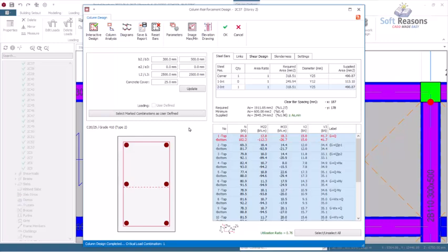You know, this column is actually carrying load, because as we are changing and working on these sections, we need to go down to the first floor to also work on the sections that are carrying that cantilever beam, which supports this particular column, the first concrete column section, successfully. So I wouldn't want to go by 25, but with these sections I've given here, I think this is the limit I can go at this level, so that the beam will not be that much deflected. The deflection will not dip that much, but I can still reduce these sections.